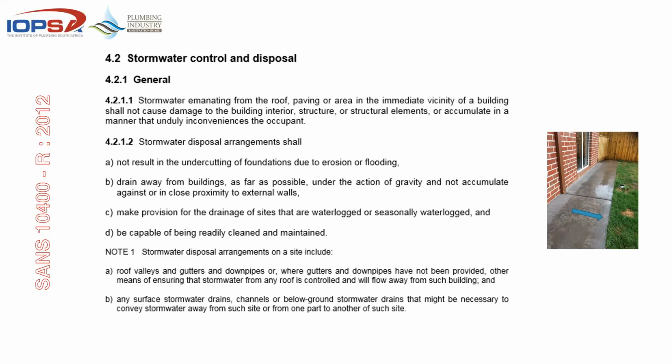Stormwater disposal arrangements shall not result in the undercutting of foundations due to erosion or flooding. Water must drain away from buildings as far as possible under the action of gravity and not accumulate against or in close proximity to walls. Make provision for the drainage of sites that are waterlogged or seasonally waterlogged.